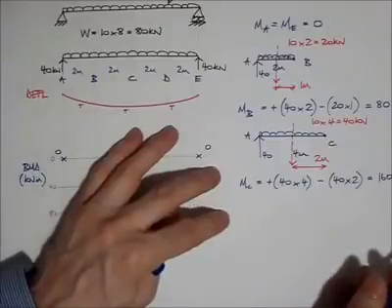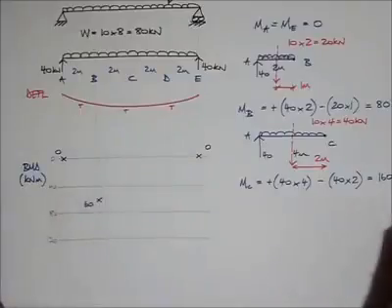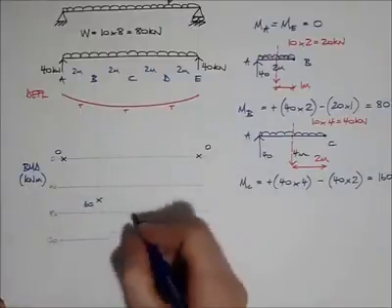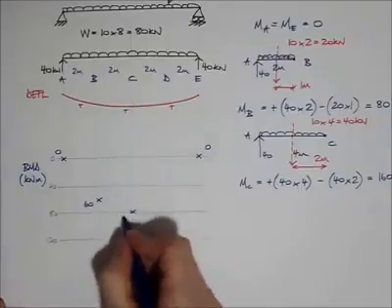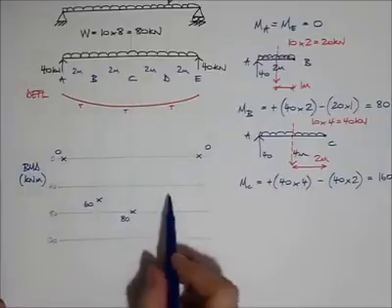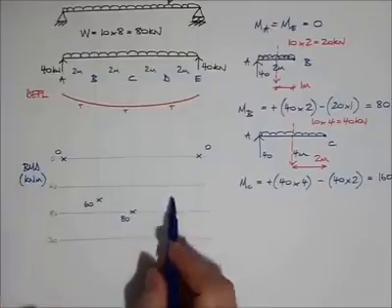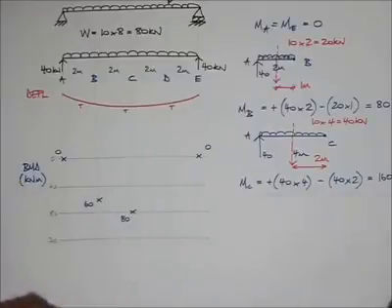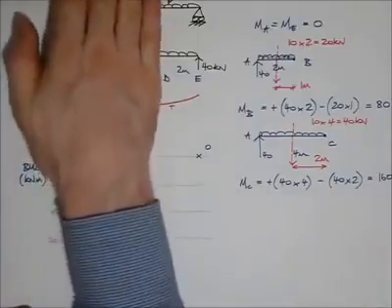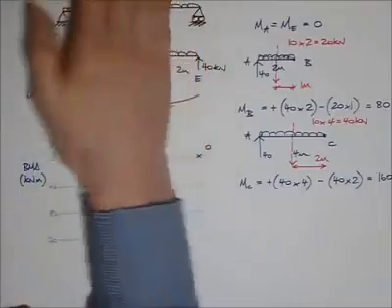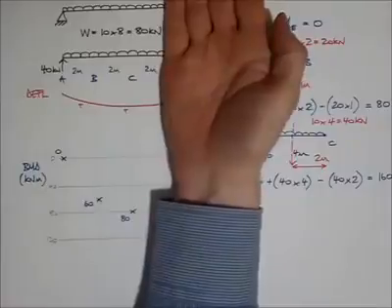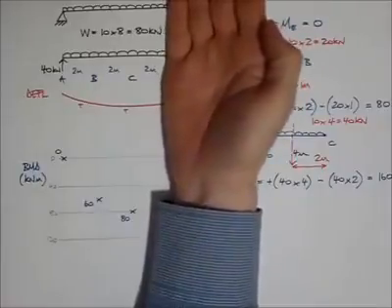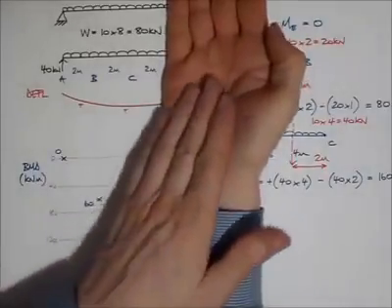Great. Mark this onto my diagram, the bending moment diagram. At point C, I'm down to 80. And now I can go to point D. That's the only thing I've got left. Now ordinarily, at point D, I can cut the beam and look either to the right, which looks pretty easy to me, or I can look to the left, which looks a bit more complicated, but I'm going to stick with the complicated way because this seems to be the way we're doing it.